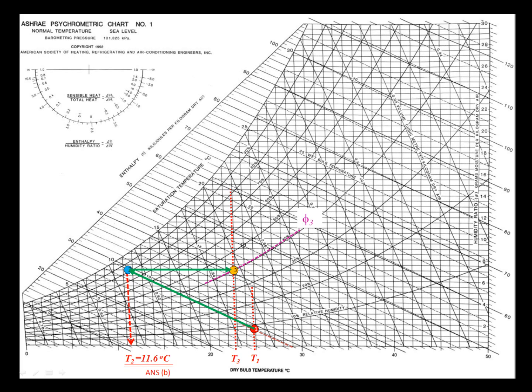If I go back to the chart, remember the mixture enthalpy is the scale here on the left-hand side. It's in kilojoules per kilogram of dry air. It's the same scale on this far right side. If I'm over on this side of the graph, I can use this for convenience, but it's more convenient to use this side. And these solid diagonal lines are lines of constant mixture enthalpy. So if you're on one of those lines, you follow the line up.